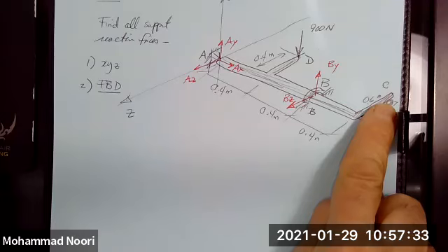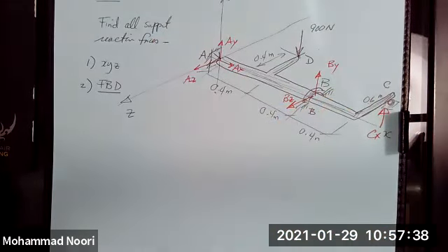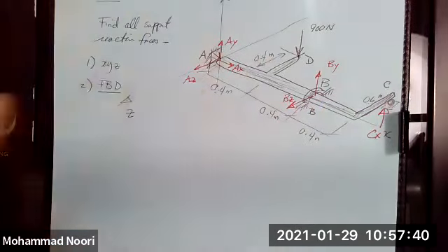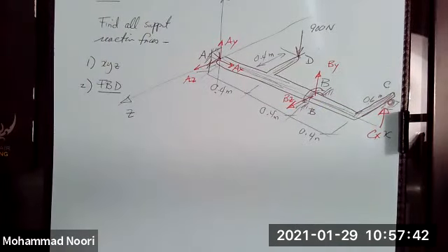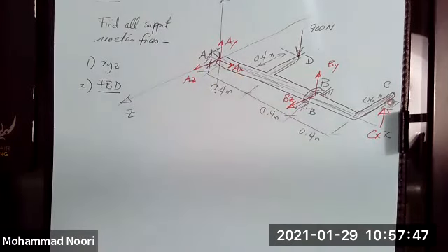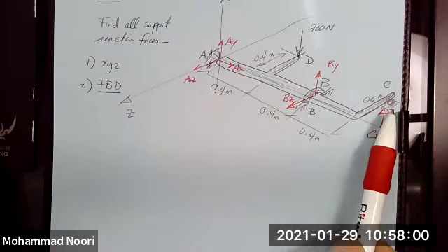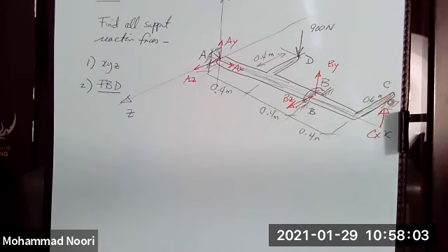As far as C, you just have this sitting on a ball. Think about you put your foot on a soccer ball. You can move your foot in two directions, but you cannot push the ball into the ground, right? That means the ground is exerting a force, and you can also rotate in any direction. So this connection represents only one force coming from the ground.